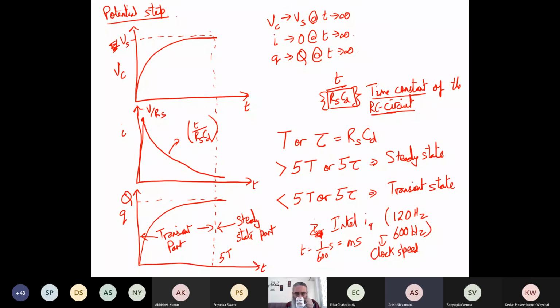If I take a very low capacitance, like nanofarad, then I'm in trouble, because the time scale of response is going to be of the order of nanoseconds, since your resistor is still finite. So measuring that would be that much harder, and I'd need more advanced electronics. When you get into nano, it's still fine. Nano ampere current is very much possible.